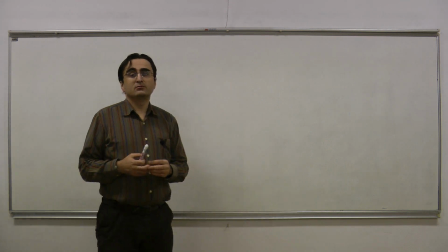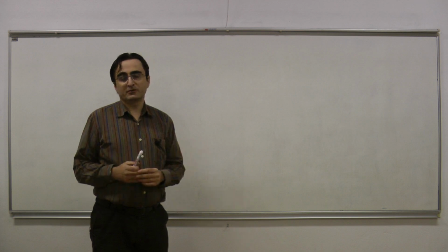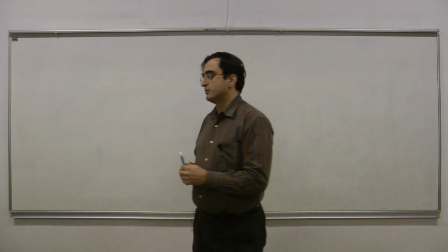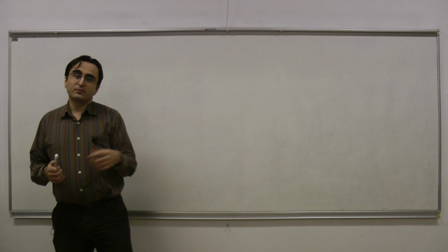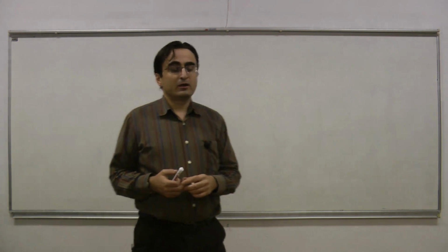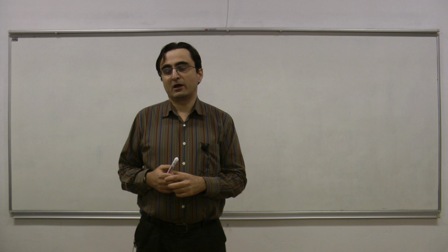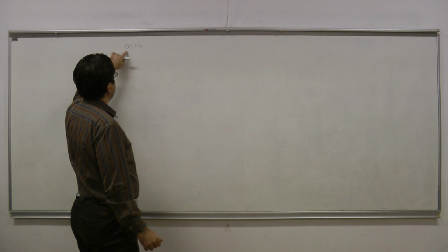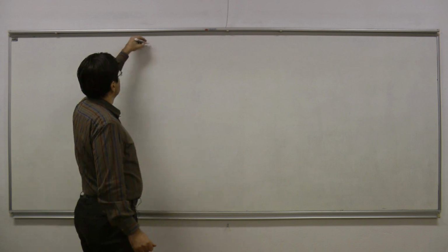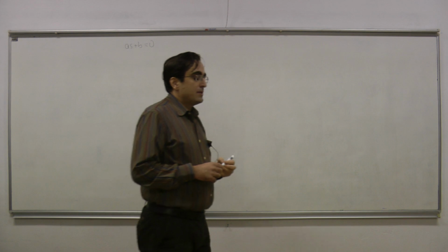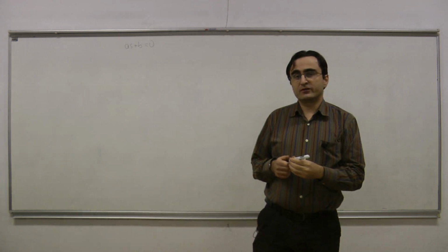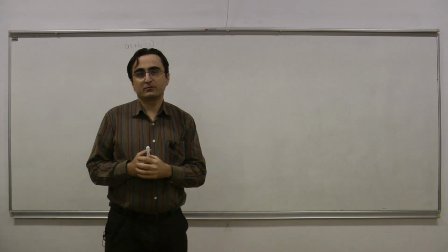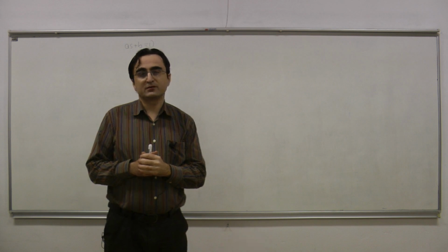We know that we're going to be dealing with real parameter systems. So when we have a polynomial in a transfer function, the coefficients of that polynomial will be all real. That means that if I have a first order polynomial, then its root is going to be real as well. So when I have a first order polynomial, as plus b, if a and b are real, then the root of this thing is going to be real. That means that when I have a first order system with real parameters, we are going to have a real pole for the transfer function of that system.